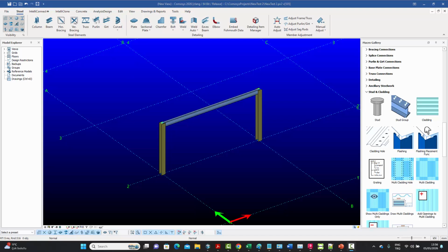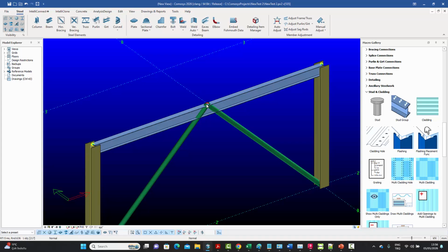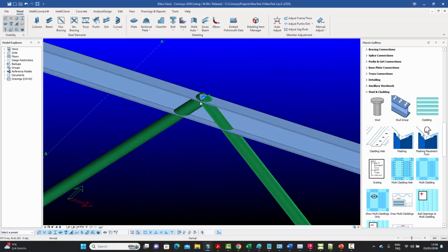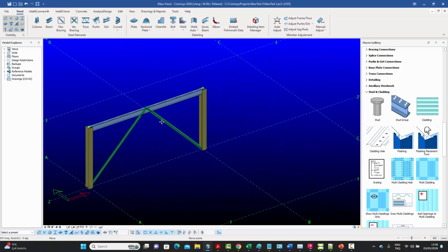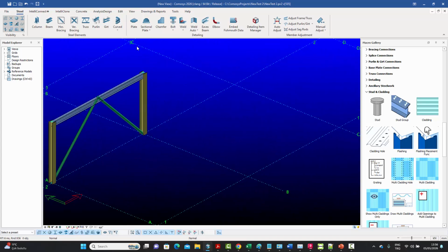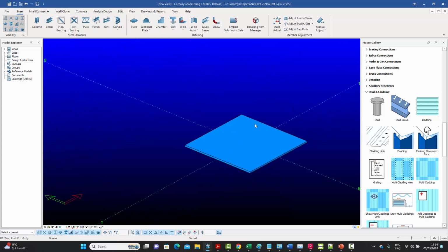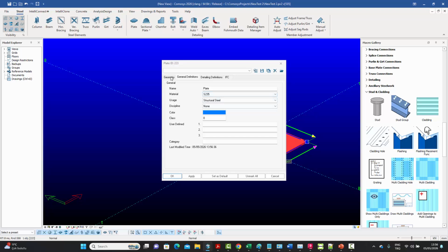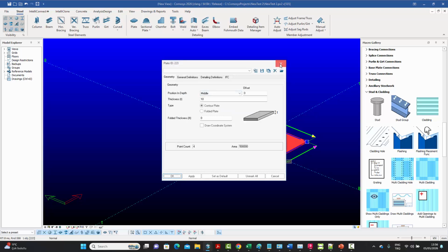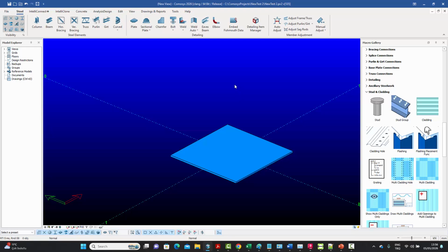Now let's enter a vertical brace, for example. Let's go like that, and like that. And previously, normally it would come out as an angle, but now it's coming out as a pipe profile, exactly the way we modified it. Now we can try entering a little plate. So let's just go in there and hover over this point, press enter and say R500 by 500 just to create a rectangular plate. Immediately you can tell that the color of the plate is the one we had chosen. And if you double click on it, the thickness is also 10 millimeters. So that default has been changed as well.